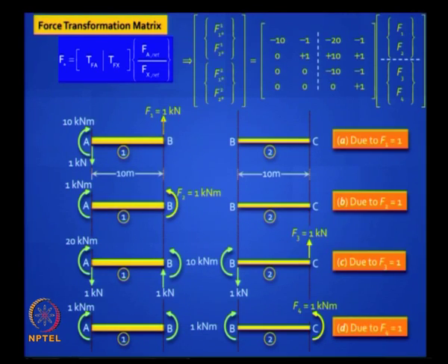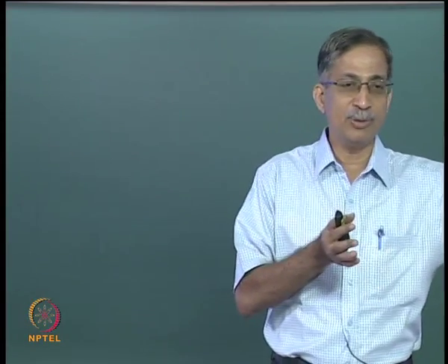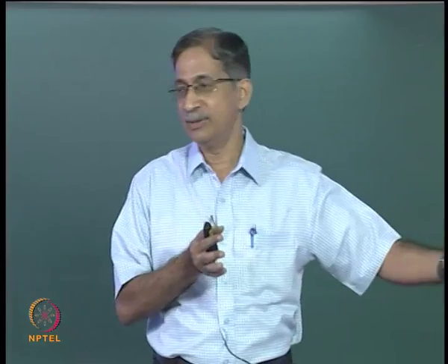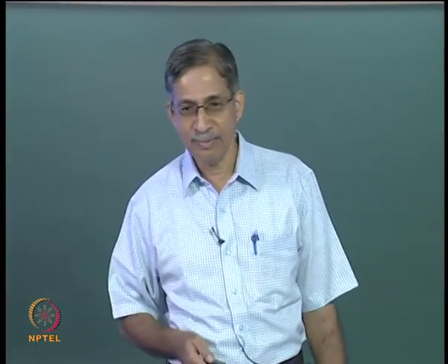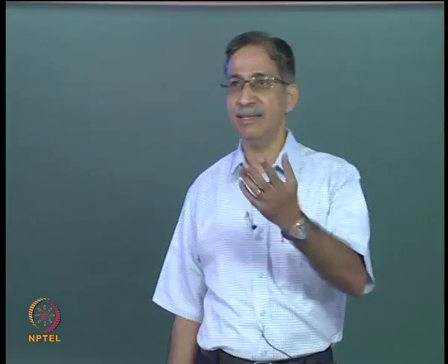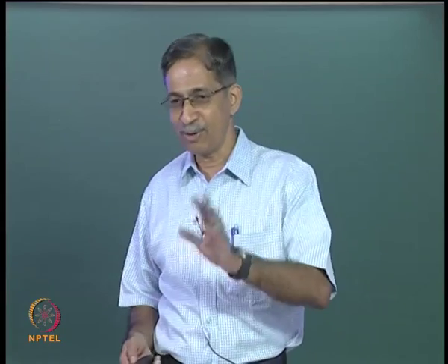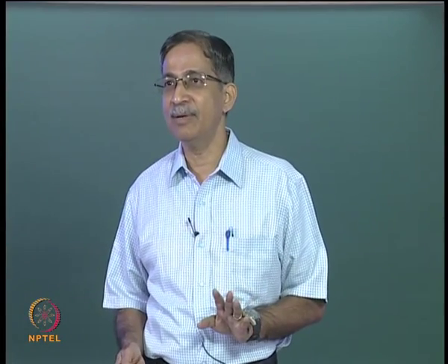Once you have got the end moments, you can find the vertical reactions, you can draw the shear force diagram, bending moment diagram, but remember this can handle only nodal loads. You also have to add the contribution of fixed end forces, for which we have to borrow ideas from the stiffness method. So let us do that next. Fixed end forces, these are very easy to calculate, we have done it for stiffness method. So you just have to copy those same diagrams for reduced elements.